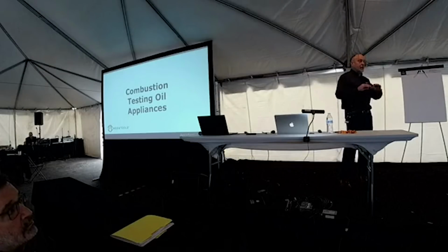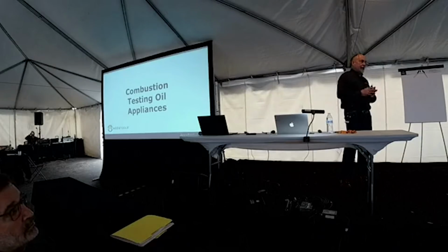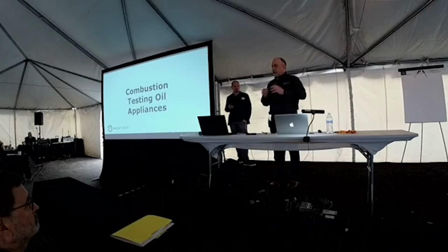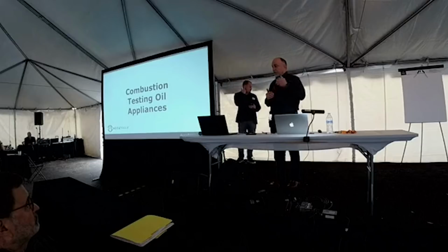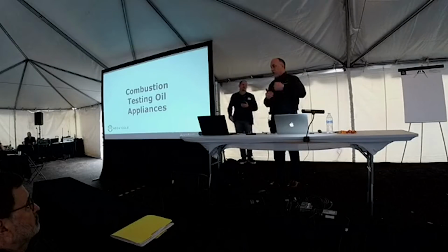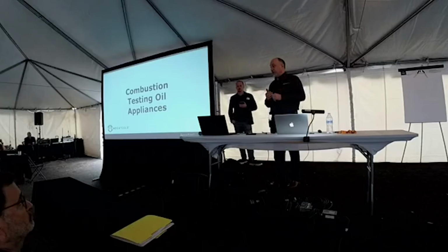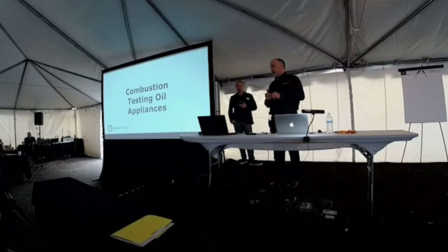But yeah, everything we do in measureQuick is set up so you can input the data by hand if you need to. Combustion is combustion, so for the most part, we always try to get the right amount of fuel and the right amount of air in there. That's why we built all the targets in for all the different appliances. When you ask how important it is, that's the profile. So we've got to make sure we get the right profile put in so we know what we expect coming out. The biggest thing that changes is your oxygen reading and your stack temperature.